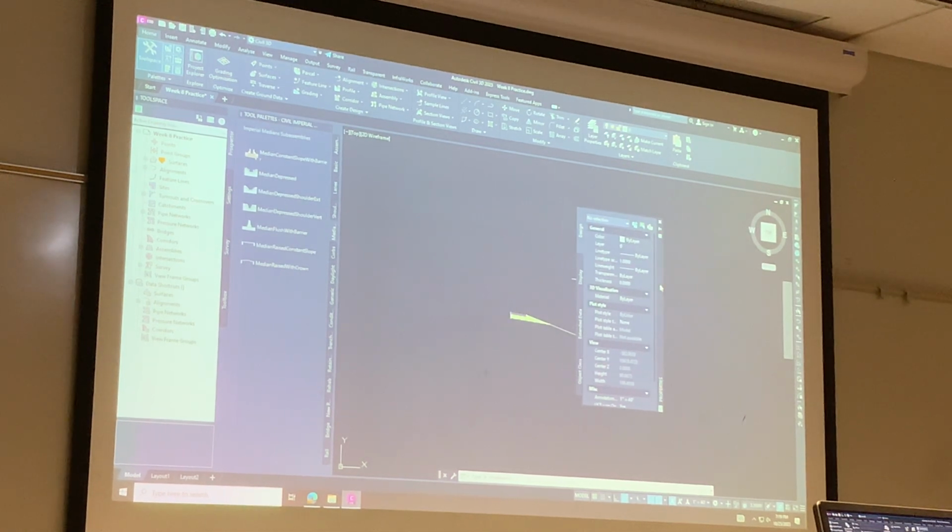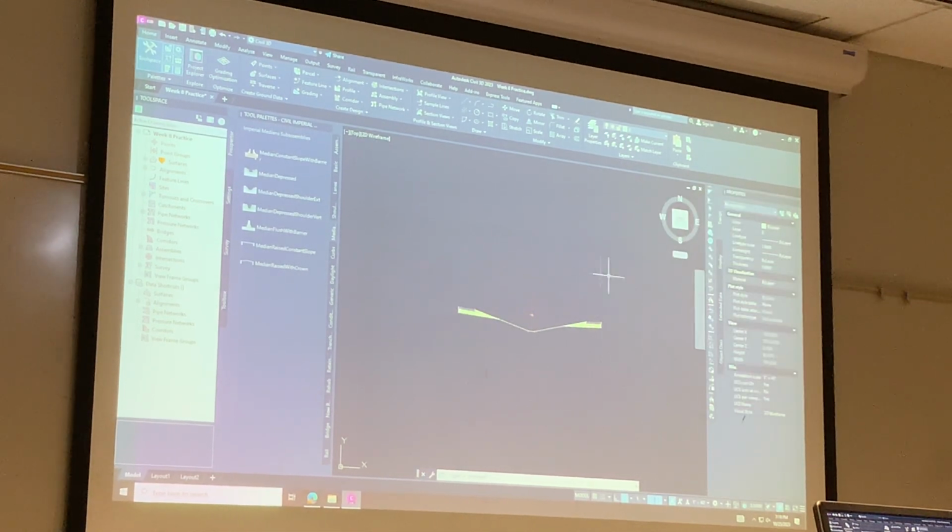Got it? Yep. Okay, and then if you want to, you can dock it, just drag it over to the right side. Uh-oh. I'm not going to do that. What happened? It's just, if I try and put it over there, it disappears. It's because you've entered the medians command. You've got to escape a couple times. I was making that mistake too. So make sure you've escaped a couple times and then enter properties without having anything selected. Yeah. I got it. Okay.